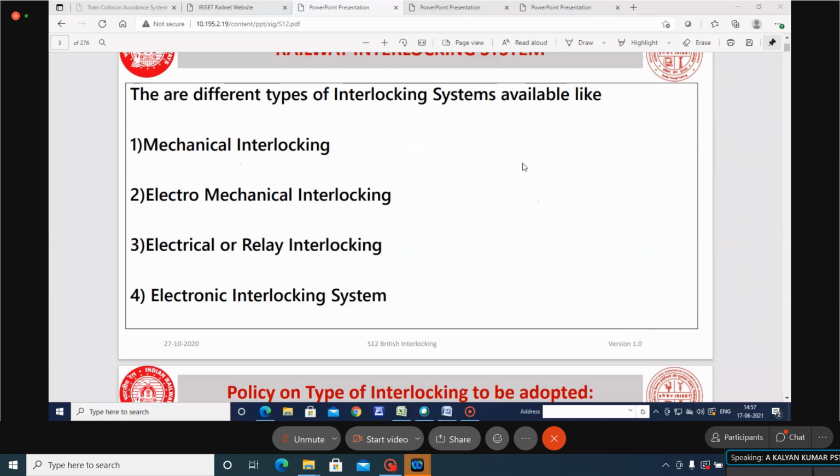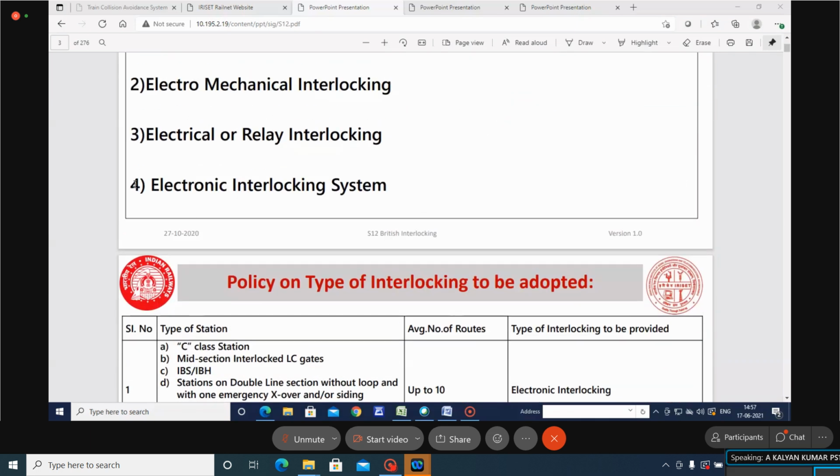And how is it achieved in electronic interlocking? Through logic circuits, sir. The same circuits we use in relay interlocking, we convert into equivalent Boolean logic circuits, and we reduce the number of relays. Most of it is done through logic, and only the necessary relays which have to drive the gear are retained.